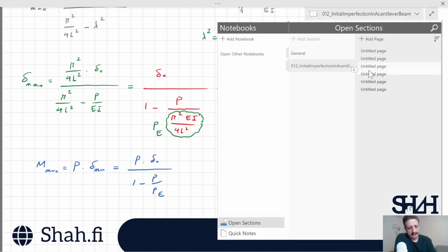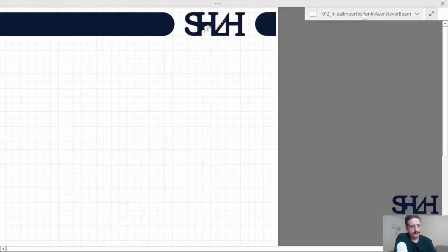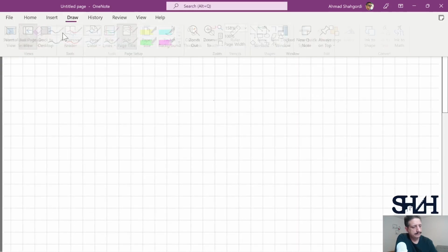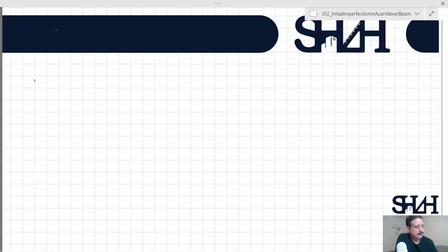Now, the next phase is to calculate the stress in the element. So the stress can be calculated according to the force divided by area as far as it's compressive, so it's negative, plus minus moment divided by section modulus. So it will be minus P divided by A plus minus.